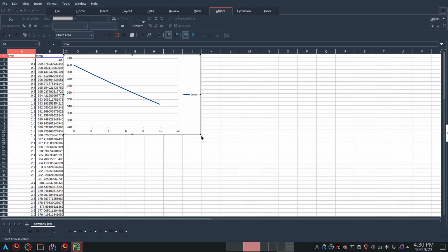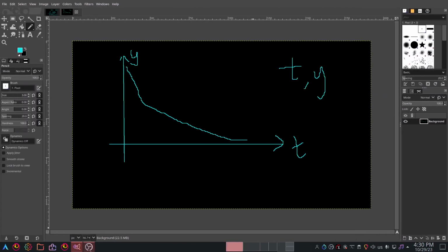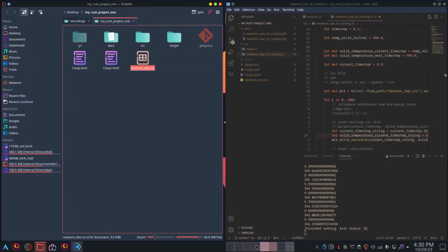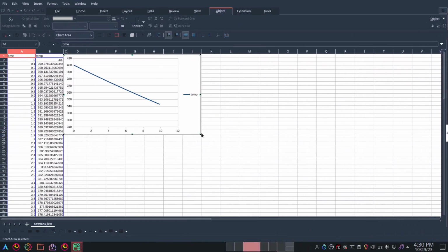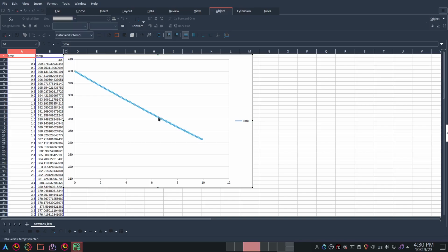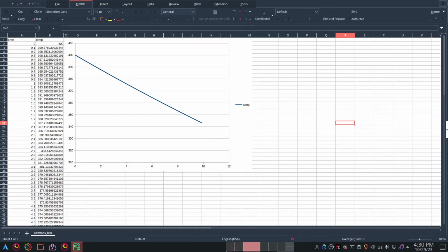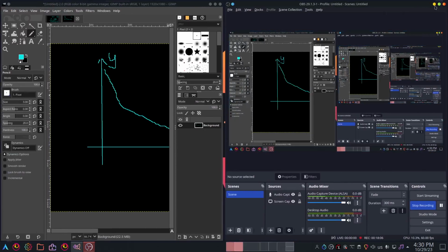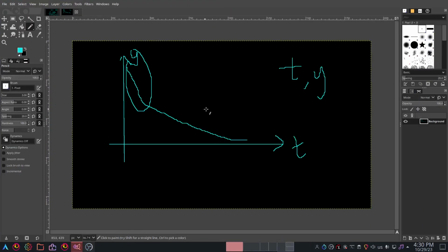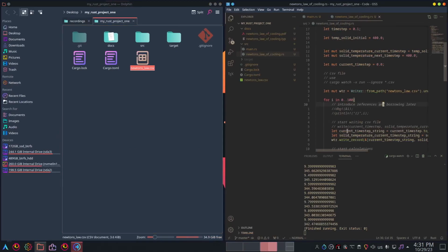Okay. So this chart seems to indicate a decreasing temperature. It looks almost linear. I don't know whether there's an actual problem with it. Is there some kind of error? Why is it a linear profile? Okay, maybe it's too early in the graph. If you take a look at this part, it can look a bit linear, and you still haven't gone to the part where it starts curving down. So maybe what we'll do is lengthen the time step.